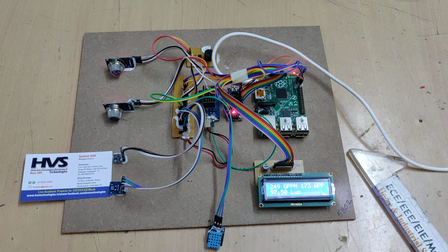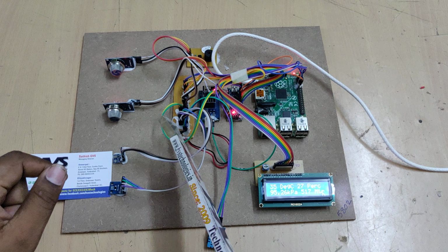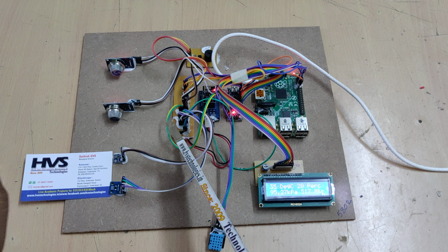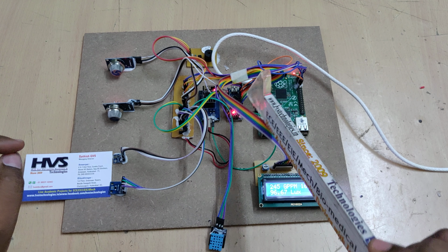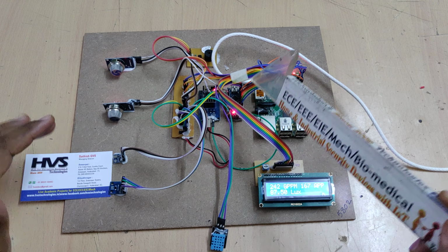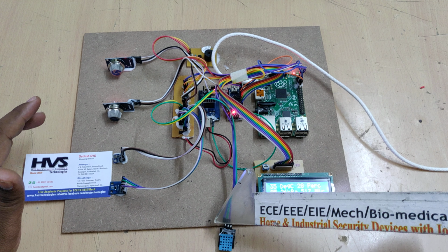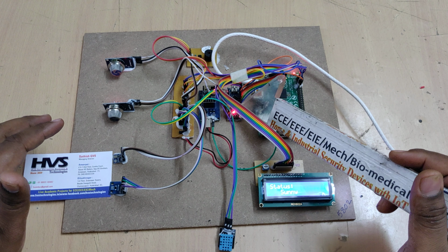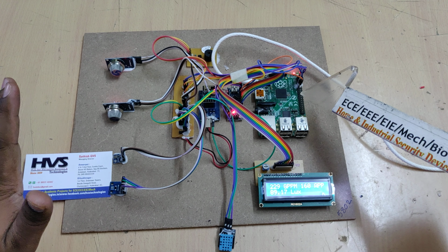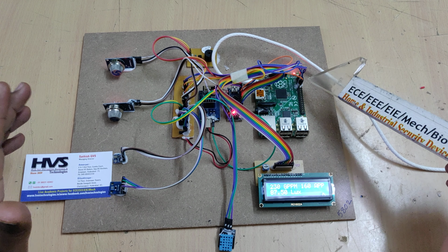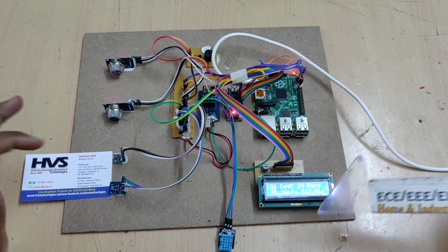Right. And coming to the interfacing connections. I have explained the components wise already, and this one is the breadboard to distribute the 5 volts power supply to the input and output modules, and next is the nano board interface to the sensors, respectively A0, A1, A2, A3, A4 pins directly interface that, and the transmitting pin of the nano board is input to the Raspberry Pi, and the Raspberry Pi, after processing the data, will send the data from the transmitting pin of the Raspberry Pi to the receiving pin of our nano board, and that will be displayed on this LCD screen continuously.